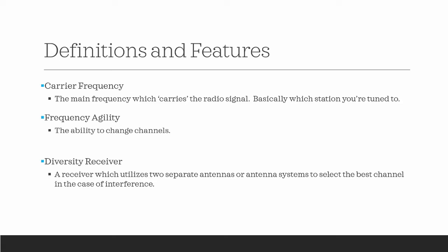It's important to know what frequency bandwidth you're going to be covering and what existing interference is going to be there. Existing interference can take many forms, from other wireless systems being used in your facility to broadcast television stations to public safety radios to all sorts of stuff. You name it, we're competing over the same frequency space. So it's definitely something that we want to keep in mind.